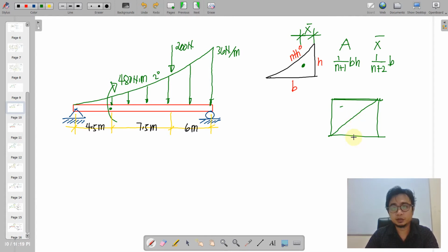So in terms of a curving line between these 2 points, if we have a second degree, of course, this area here would now become 1/3. Applying this formula, we have 1/3 base times height. Of course, the remaining here is 2/3 base times height.